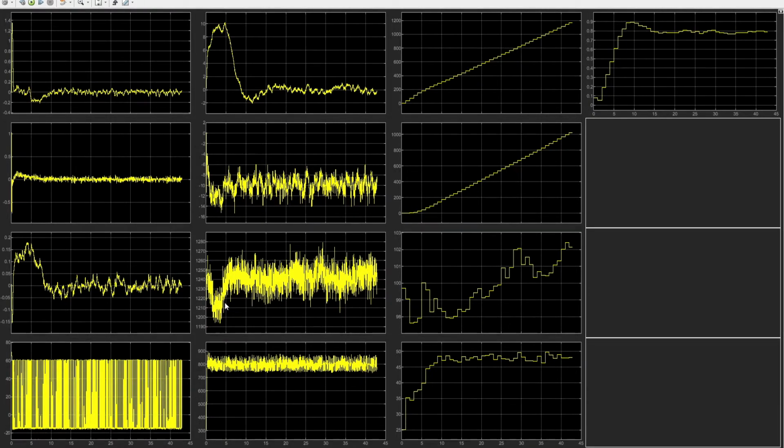And finally, we have our different pressure values here that come from static and differential pressure based on the altitude and airspeed of the vehicle. Both these numbers also seem to be about correct. Then we can move on to our GPS sensors here that show the heading in the X and Y direction. As you can see in X, it starts along a constant velocity and basically maintains that the entire time, and in Y, you can see as it slowly turns into that direction, it starts heading on a constant velocity as well.